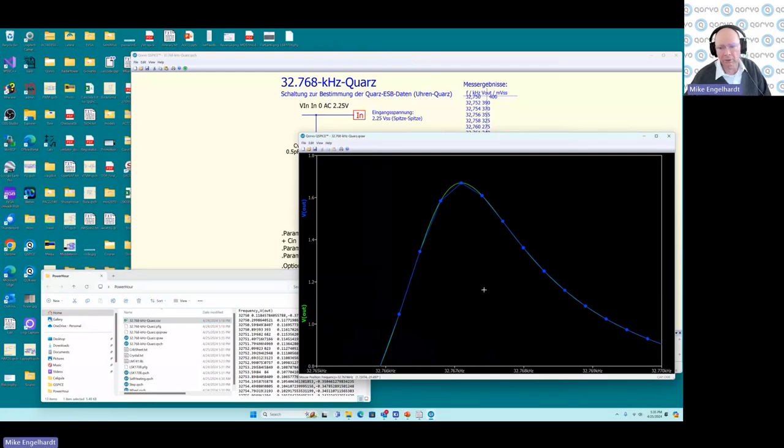Now, there's something you should understand about overlaying waveform data. SPICE users don't overlay. They use something called dot step, which means they set up the simulation so it runs the same simulation many times with different values of a parameter. That means all the waveform data is in the same address space, and so the GUI can be perfect as far as labeling everything correctly. If you just overlay data from different simulations, there's no way you could know that it's correct.